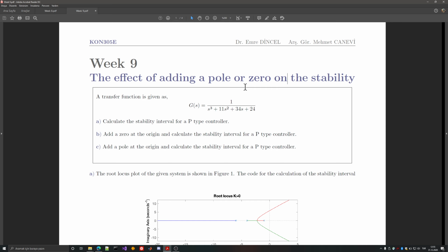PI control is basically looking for a place for the zero, since the pole is fixed at the origin and you have the system, and then choosing a gain. So there are 2 steps to design a PI controller: place a zero and then choose a gain. So if you do that, you already have to add the pole at the origin and you will be good to go.